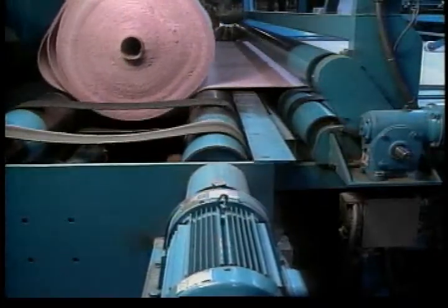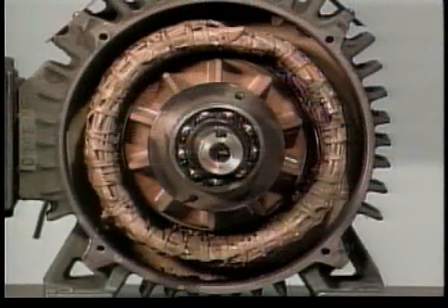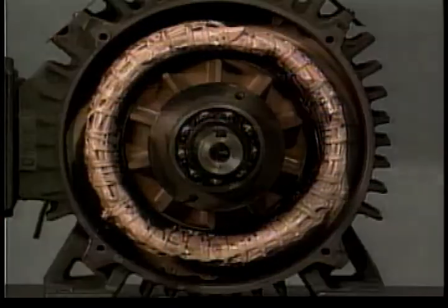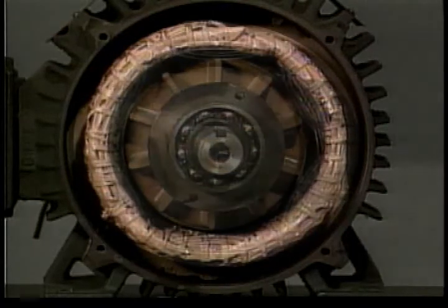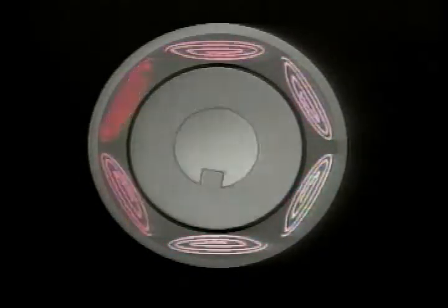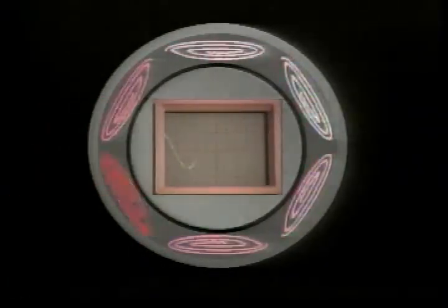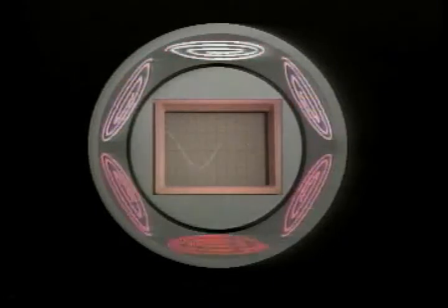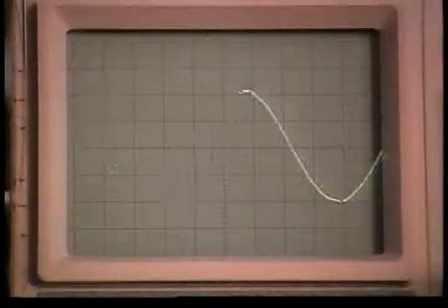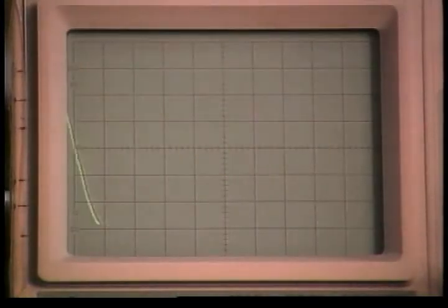To understand how inverters control speed, torque, and power, let's look at a typical three-phase induction motor. When current is applied to the stator, it creates positive and negative magnetic fields that revolve through the stator. The rate at which these magnetic fields revolve depends upon the frequency of the applied current. The lower the frequency, the slower the magnetic fields revolve. The magnetic strength of the fields depends on the voltage applied at a particular frequency. The higher the voltage, the stronger the field.